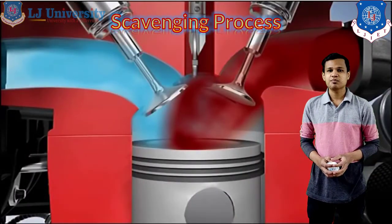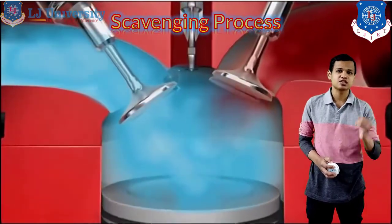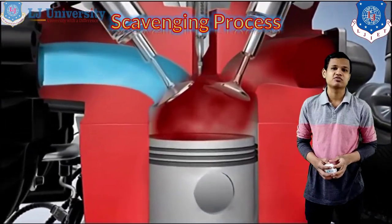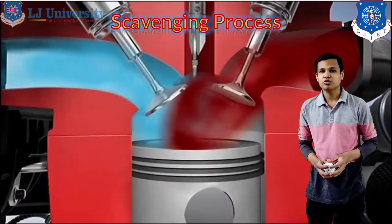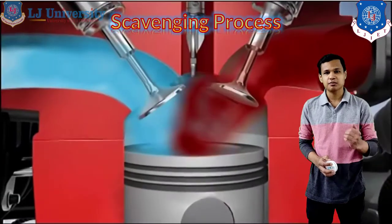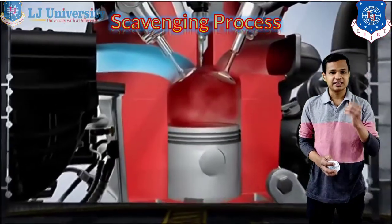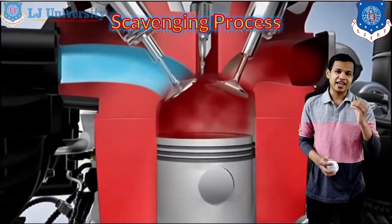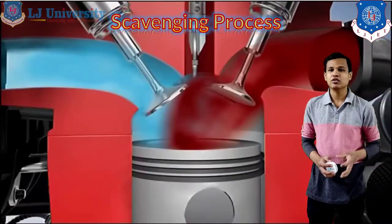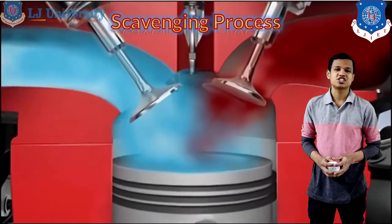What the scavenging process provides is that the inlet charge forces the exhaust gases outside via the exhaust port. For that, we will have to pressurize the inlet charge before supplying it into the engine. Because of the high pressure of the inlet charge, the exhaust gases will be forced out. That can only be achieved by pressurizing the inlet charge.